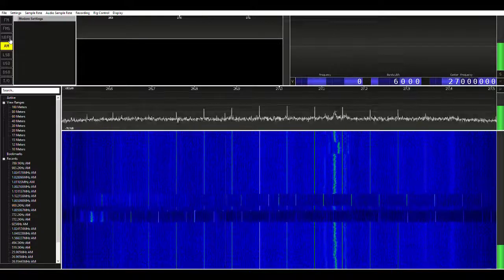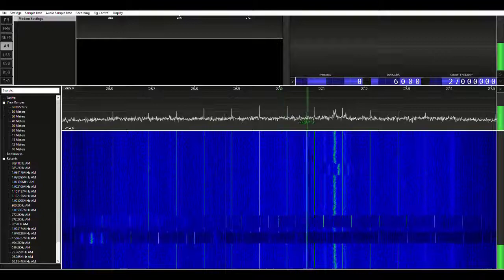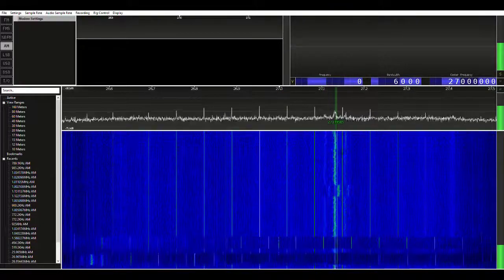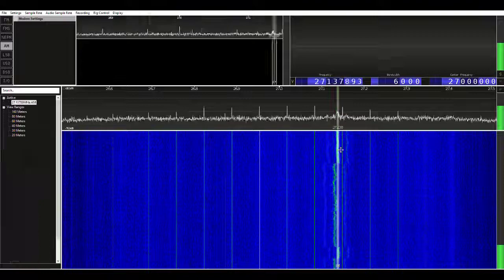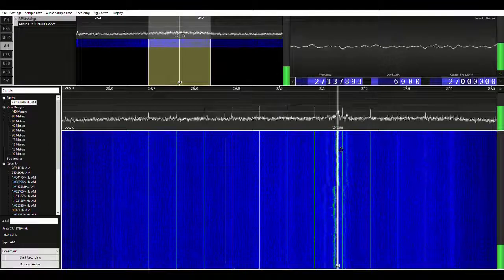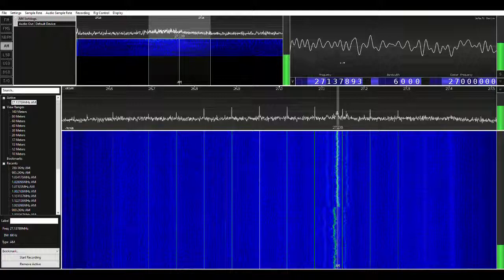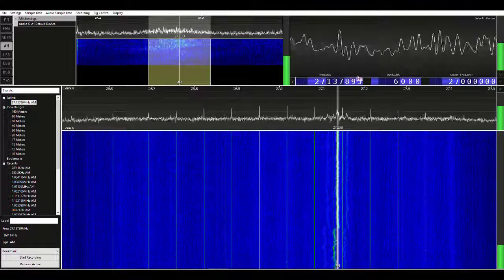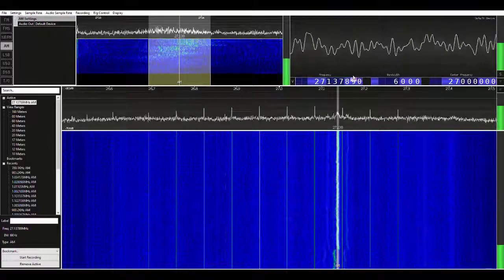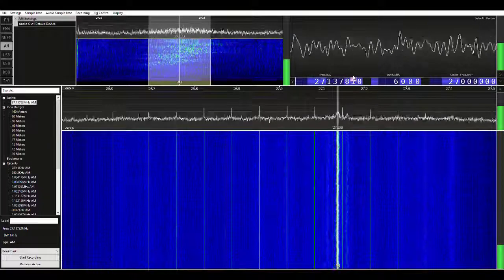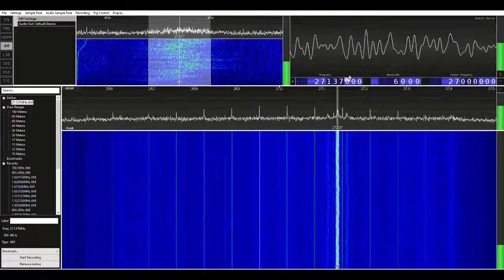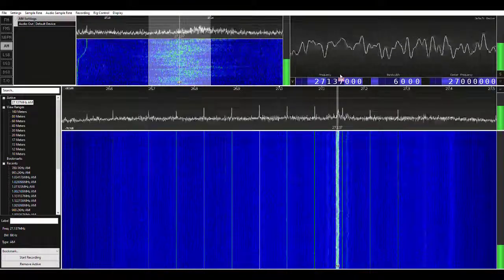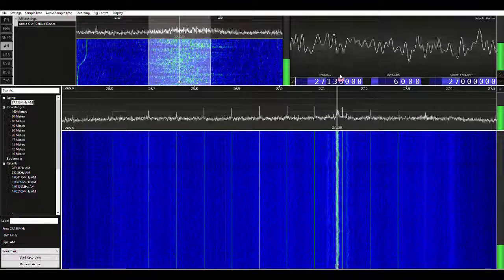We're ready to instruct the SDR to act as an AM receiver by clicking here. Now we'll search for CB channel 15 at 27.135 megahertz. We hover the mouse over the carrier we want in the waterfall and click. We use the mouse to adjust the carrier frequency to channel 15. You'll notice that the best centered frequency may not be exactly 27.135 megahertz on the screen. This is because the local oscillator in our little SDR may be drifting slightly from the exact frequency, so we have to search for the signal.